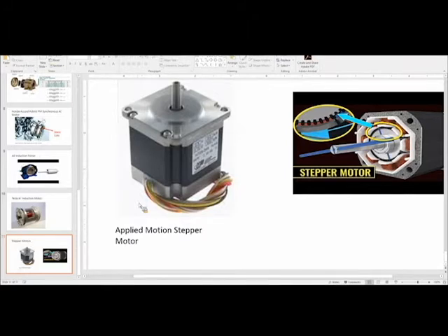To get the next step, de-energize coil B and energize C. Okay, so I hope it's clear why it's called a stepper motor, because as you fire these different coils, you are stepping in rotation. So A, B, C, A, B, C, right? If you ever wanted to go back, say it's in a configuration aligned with C, if you wanted to go in reverse, you would then energize B, right? So you could step back and forth with this type of motor.